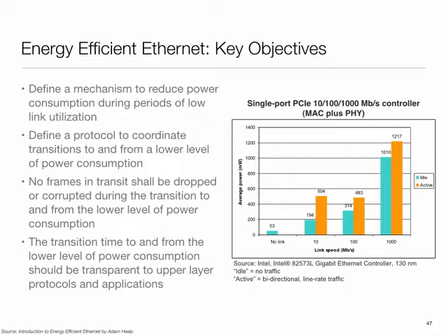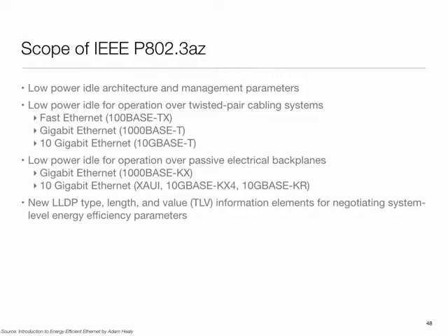So for the actual standard, they set out certain goals which took this into account. Eventually, what they ended up with was this notion: LPI stands for low power idle. Basically, the idea is that during the idle mode, I could switch to essentially the equivalent of shutdown. So the upshot of all of this is that instead of scaling the speed, it was decided that when idle, I could switch to a very low power mode where I can idle in a very power efficient fashion.